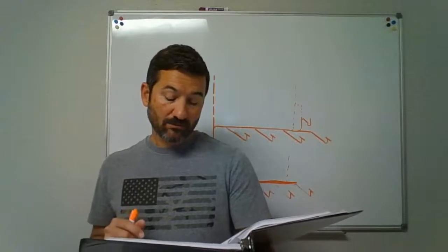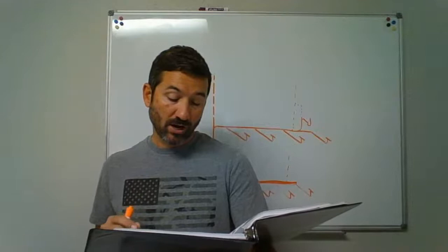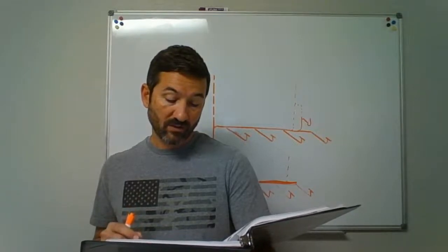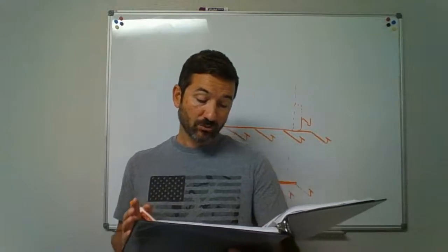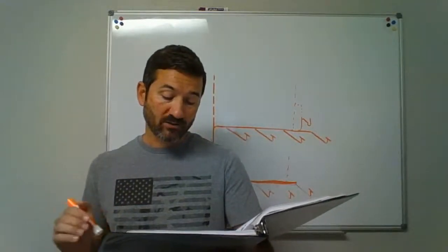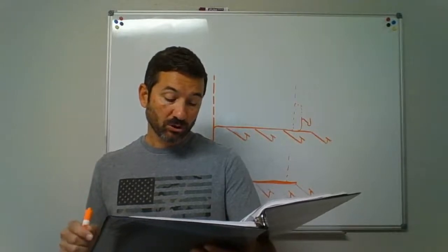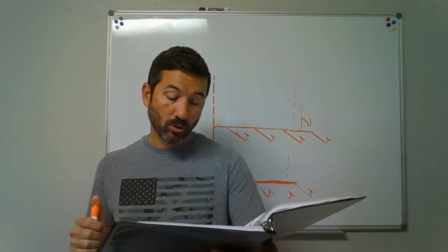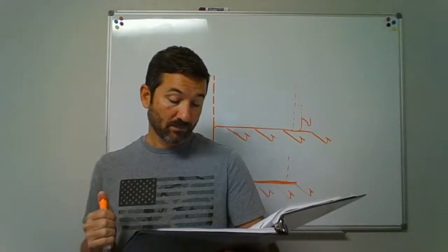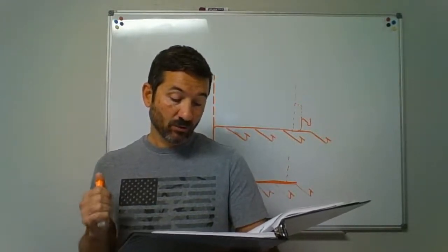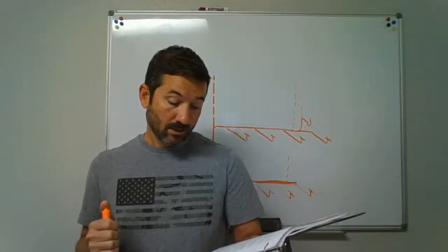The vent connection. The island fixture vent shall connect to the fixture drain as required for an individual or common vent. The vent shall rise vertically to above the drainage outlet of the fixture being vented before offsetting horizontally and vertically downward. The vent or branch vent for multiple island fixtures shall extend to a point not less than 6 inches above the highest island fixture being vented before connecting to the outside vent terminal.